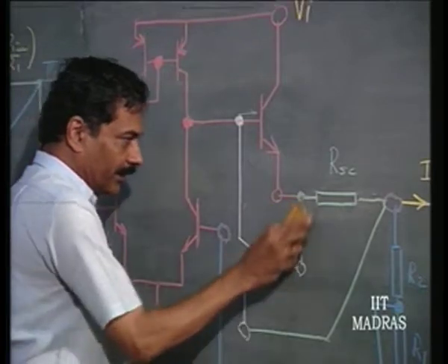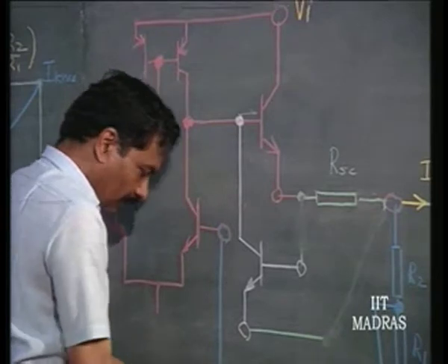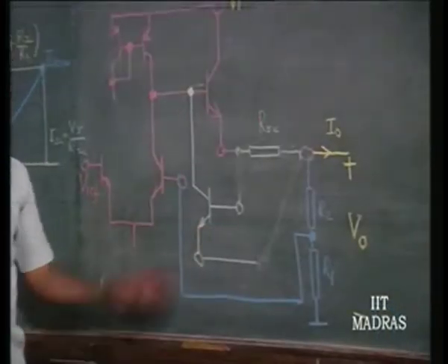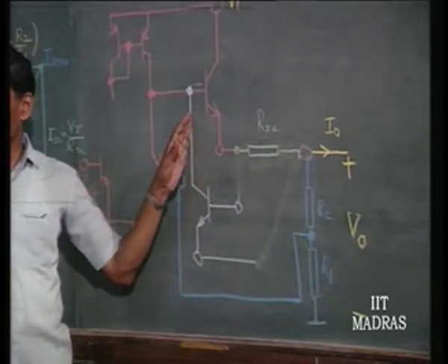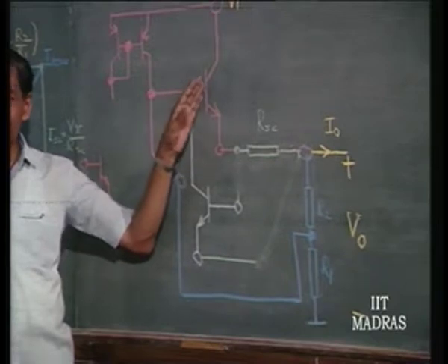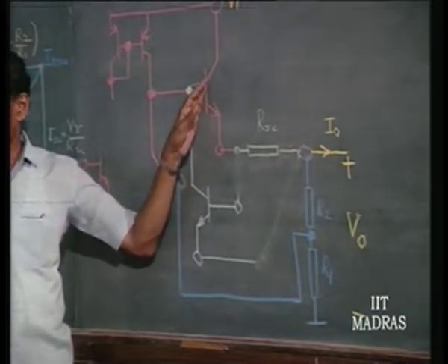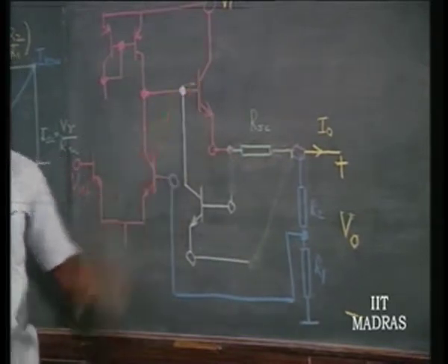We will remove the old scheme. The same transistor is now going to be used to divert the excess current drive into the series pass transistor. That basis of diversion is still followed, but the method adopted is now different. How do we do it?